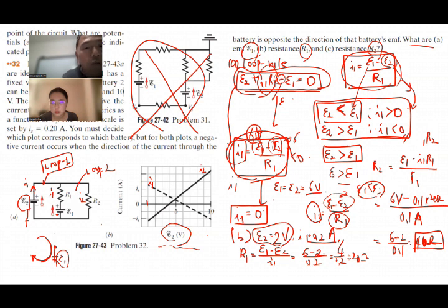This one is maybe 0.15, 0.13, or 0.14. You don't know. But if you choose 2 volt right there, that is right on 0.2 amps of current I1. Because this grid shows you the exact value of I1 and I2 if you choose a specific value of E2. So this is not a number I found. I just chose this number to find I1 from this graph.